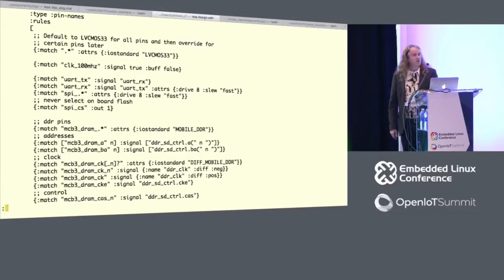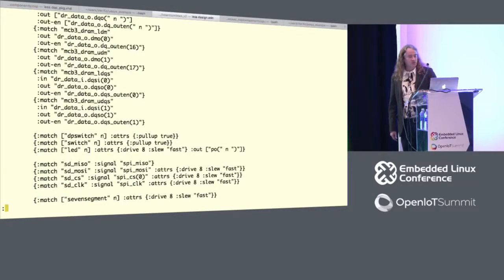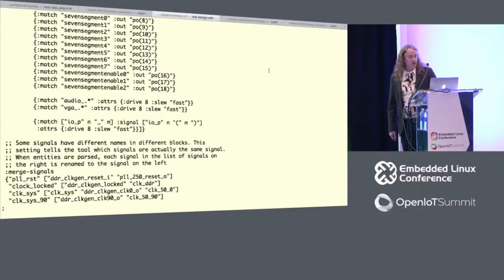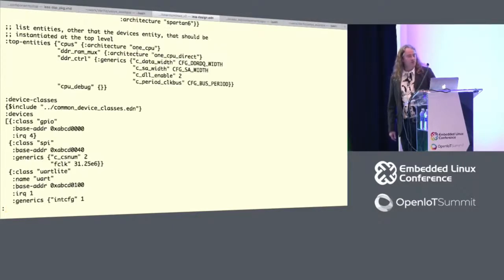You also can get out of this the data sheet for the chip. The thing that's missing right now is device tree. Once that's integrated, it will be very simple. You just add another UART in the device tree, just drop it on the board, and away you go. And you can see that it's not very difficult to do this stuff. You essentially just drop in here, I want a cache controller, and here's where it connects internally. I want some LEDs, and this is where I drop them, and they're controlled by class GPIO.